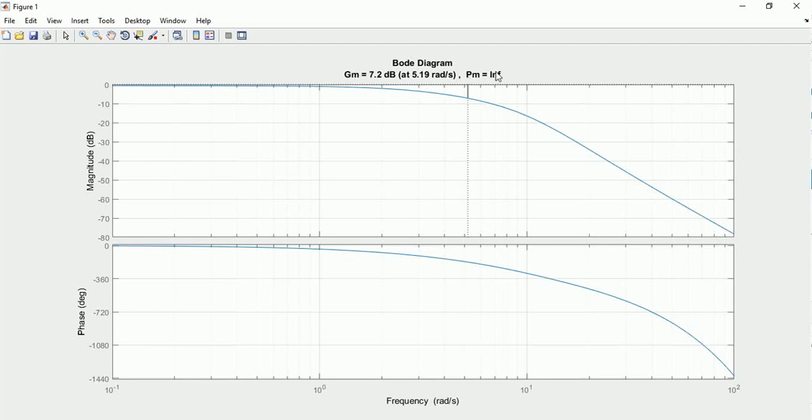The phase margin was untouched, it's still infinite, because remember our condition, nothing here was going to be affected, and it wasn't. So with the inclusion of the new filter, so far this filter seems to be good.